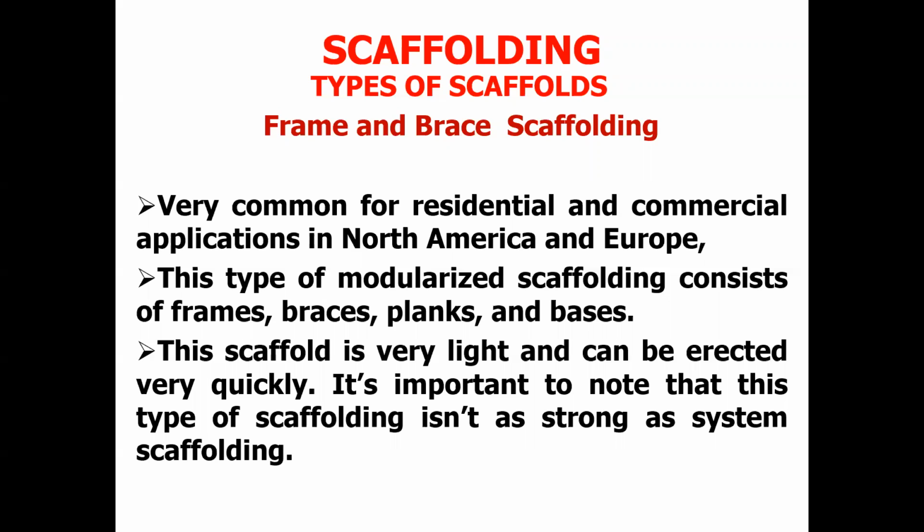You need to understand that this system is supposed to carry a human being working on the scaffold, support the equipment that person will be using to work, and at the same time support whatever building elements are being placed at a particular height. So these are the things you need to consider before you determine the type of scaffold you are going to use for a particular project.